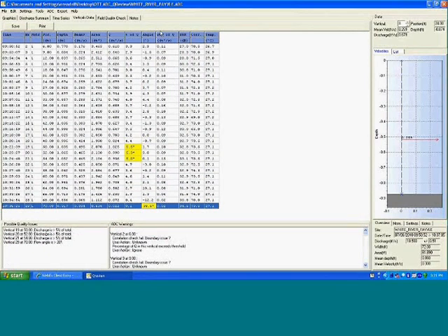Now if I'm interested in learning more about what that flow angle was, I can simply click on the flag and it will take me to the vertical data. Here in the vertical data, I can view what the actual angle was for that vertical, and I can see here that it was 38.5. I can also see other information about the measurement that occurred at that particular vertical. For example, the standard deviation, the signal to noise, the average correlation for beam 1, beam 2, mean velocity, depth, area. The Verticals Data tab also shows what corrective action was taken at that vertical.